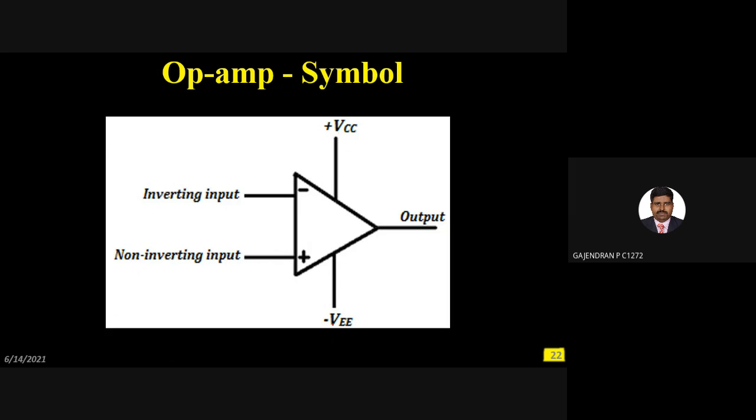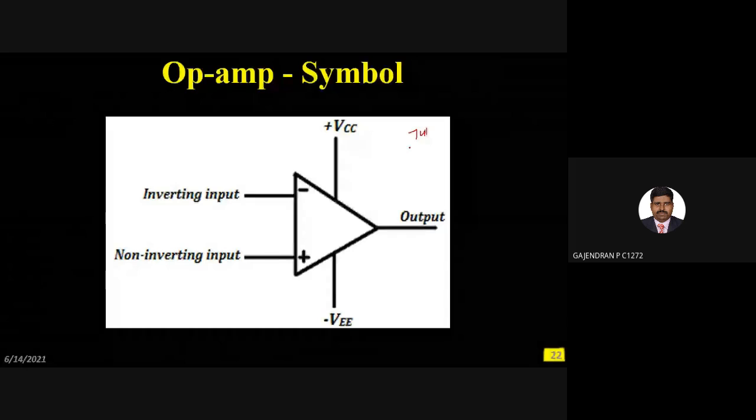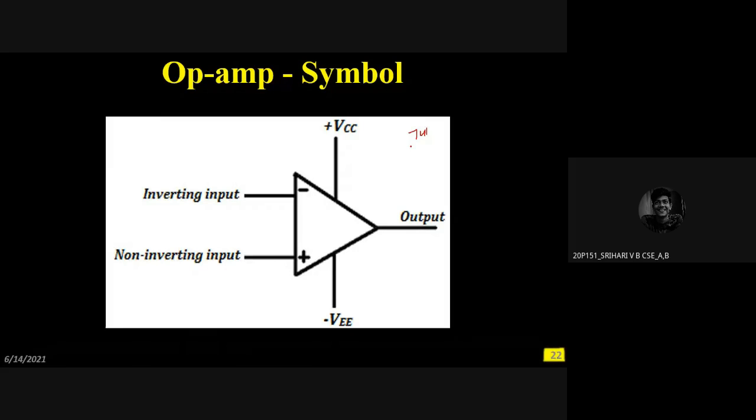Also I have mentioned, if this is my 741 IC, µA741 or LM741, what did I tell you about the supply voltage? Plus or minus 15 volt I can use, or I can use plus or minus 12 volt also.